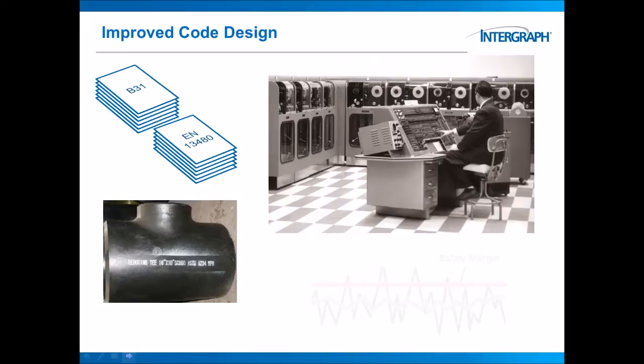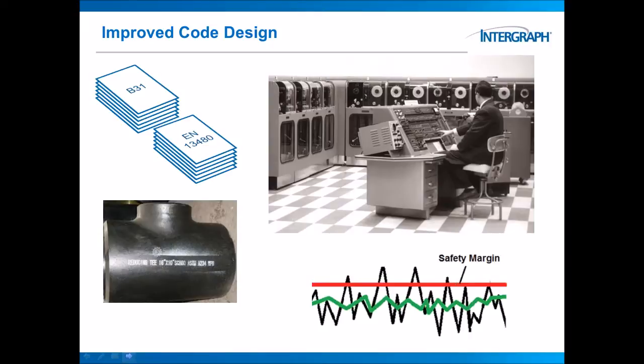And because these intersection stress intensification factors and flexibilities can be, in some instances, inaccurate, you have the possibility to exceed or go over your safety margin, following the black line shown here, which, of course, is not what you want to be doing.